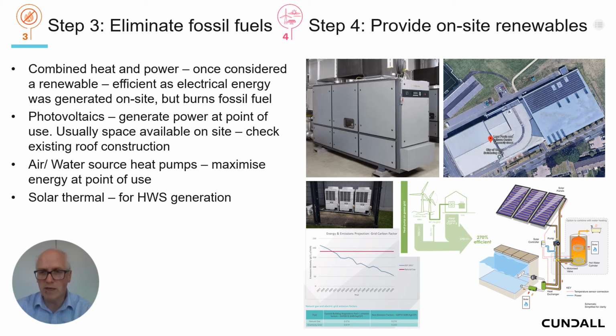The little green diagram in the middle indicates that for every kilowatt you can generate from your wind turbines or PV, you can get effectively 3 kilowatts of heat or cooling from your air source heat pump. Solar hot water is another good technology, quite often misunderstood and quite often installed on pools and then switched off because people don't understand how to maintain it or run it. But with a little bit of training, it can be another good source of, if you like, free energy and carbon-free energy.